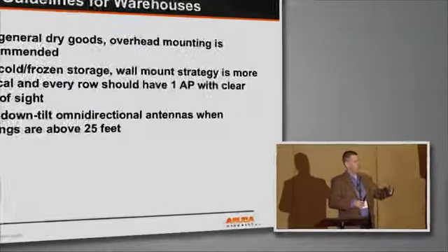So what we've done in those cases is I may have an AP134, an AP with external antennas outside the freezer, and then the antennas inside the freezer, directional shooting down the aisle. I may do a dual band antenna so that I can put a 174, an outdoor AP with a built-in heater at the far end that I mesh back to the 134, and it provides a 2.4 cell from that other end coming back. So you've got wireless backhaul, but you're still powering.